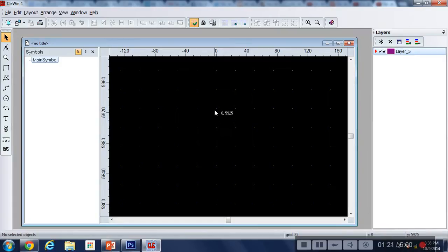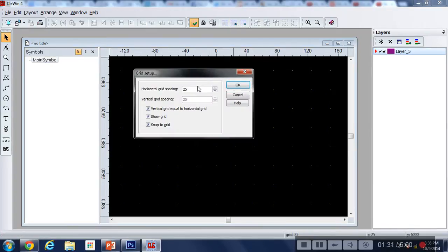So what uses a grid? A grid is very useful because all vertices in your mask have to sit on a grid point, and you can adjust this grid spacing depending on how big your features are. For example, microfluidics does not require you to use features that are less than say 10 micron, because that will go into the domain of nanofluidics.